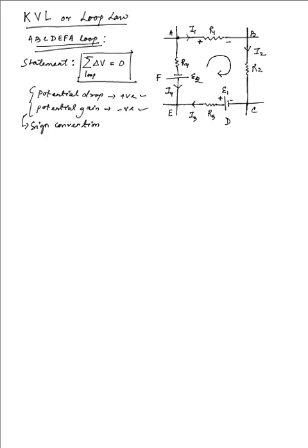So we have a potential difference across AB. So this is just the potential VA minus VB, and as we move along that, what we have is that is equal to I1 R1, and obviously I1 multiplied with R1 will be taken as positive in this case, because the sense that we are going in, we will be moving from the positive end towards the negative end, and hence we'll be having a potential drop over there.